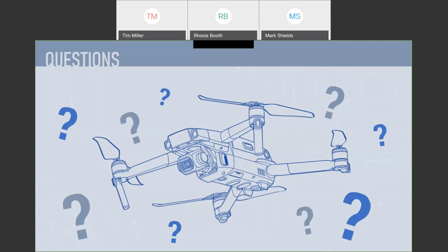And then another question: if you're not supposed to fly over people, how difficult is it to fly over to observe schools? Well, that's another good question. That's one of the waivers you can actually get from the FAA. If you're flying in restricted airspace, it's usually an instantaneous yes or no. But with things like this, you would have to submit a waiver 90 days before the mission, and then you would get permission to do so. In a situation with a school, the school counts, the drone was stationary. It sat in the air in one spot the entire time, and that spot was roped off. Nobody can walk directly under the drone. That's the interesting thing, specifically with tethered drones: you put them in the air, they stay right there.